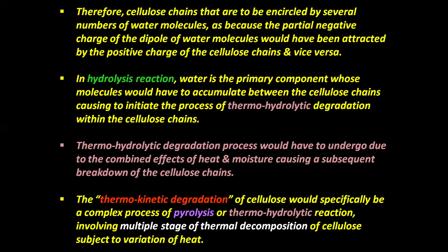In the hydrolysis reaction, water is the primary component whose molecules accumulate between the cellulose chains, initiating the process of thermohydrolytic degradation within the cellulose chains. The thermohydrolytic degradation process occurs due to the combined effects of heat and moisture, causing a subsequent breakdown of cellulose chains.